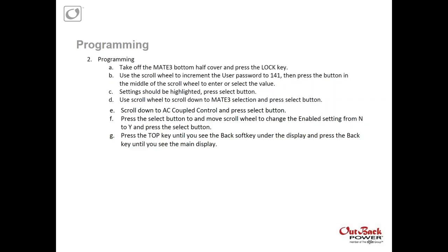You're going to go into the inverter section, and you will scroll down to where it has AC coupled. When you press that select button, it's going to ask you whether you want it to be enabled, and you will say yes. And what it's going to do at that point is automatically look at the voltage, and based on the batteries that you have, when the voltage climbs too high, it is going to flip that relay into an off position after the delay that you put in there.